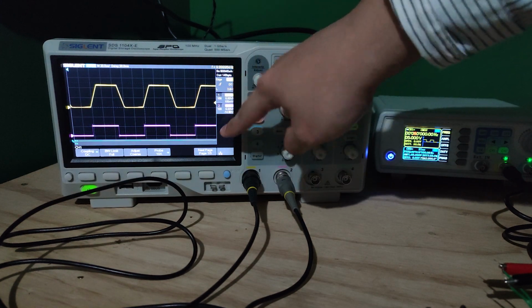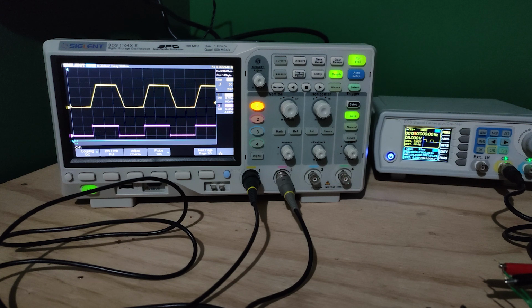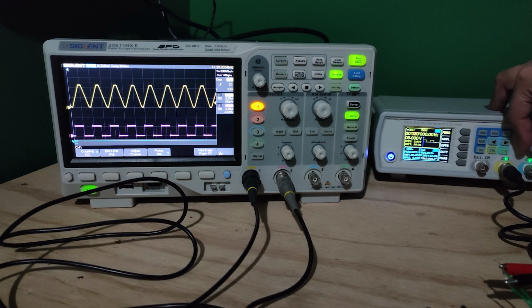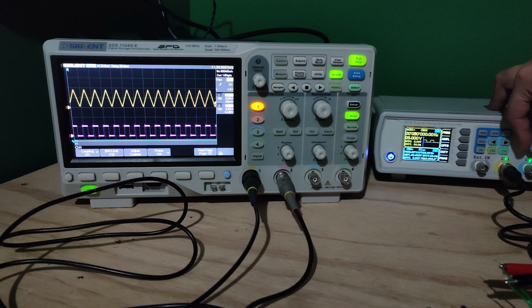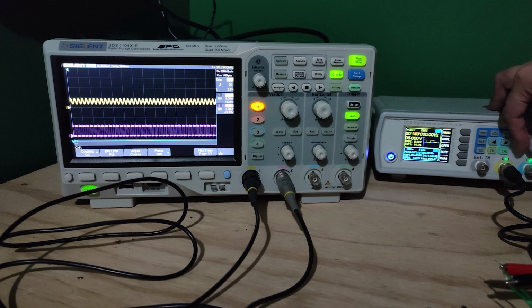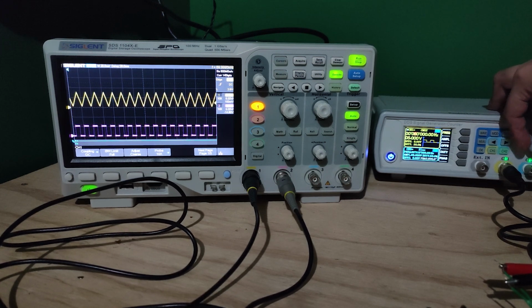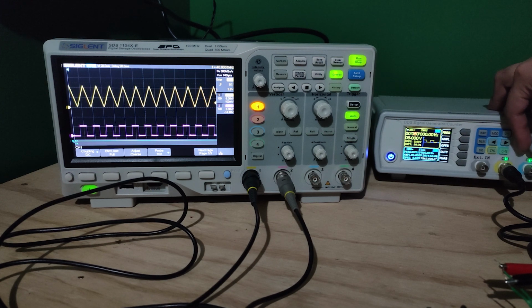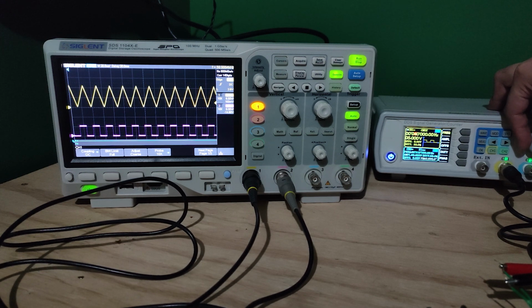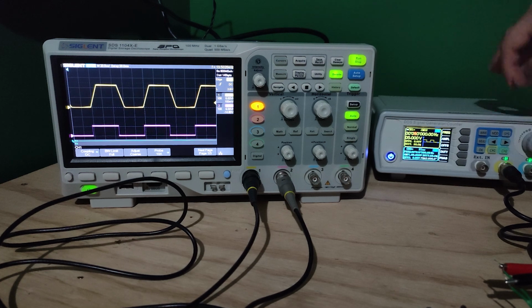This OPAMP has a relatively low bandwidth, so we're going to see issues quite right away. Here we have 10 kHz. Above we have the output signal, below we have the input signal. We have a square wave, and we're going to increase the frequency. We have other things at hand, like slew rate and other stuff, but we can see how increasing the frequency alters not only the shape of the waveform, but also the gain or the amplitude of the waveform. So we have to keep this greatly in mind when implementing our OPAMPs.